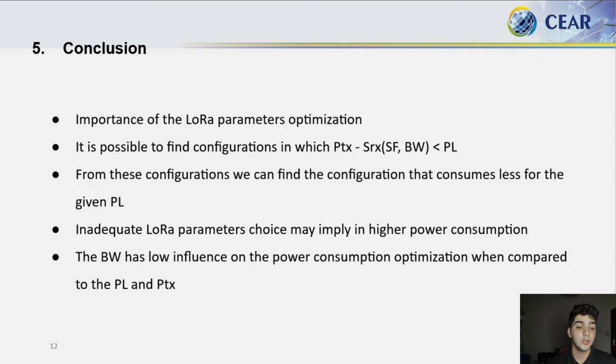Experimental results showed that the spreading factor had an enormous significance in the energy consumed by the sensor node to send packets. However, the range of the transceiver also decreases with the reduction of the spreading factor. Thus, the transmission time and RSSI can be essential information in the calibration of LoRa parameter settings. Otherwise, there is possibly a trade-off between the spreading factor and the proportion of received packages, which can be studied in future works.